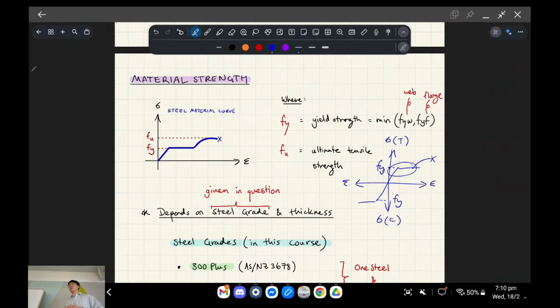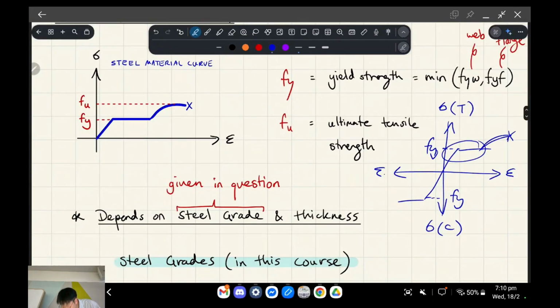A ductile failure mode just means something that's not going to fail immediately. So that cheesing effect I'm talking about, say we pull this and it's made out of metal and it starts to become like cheese. That's yielding, so that's a ductile failure mode. But if we keep pulling it, it might snap. That's a brittle failure mode. In material tests, this is represented by a pretty sharp drop in its graph values, and that value is called Fu, pardon my French. That just means its ultimate strength. Okay.